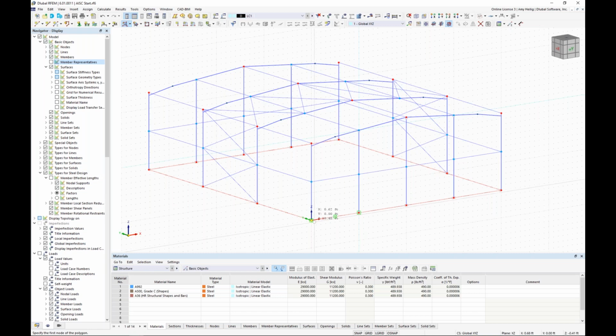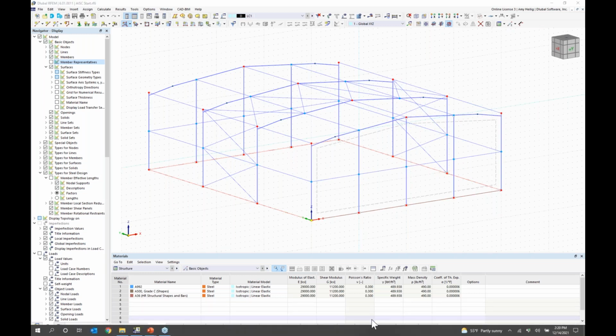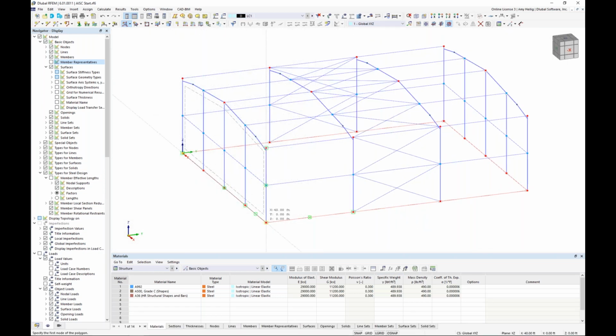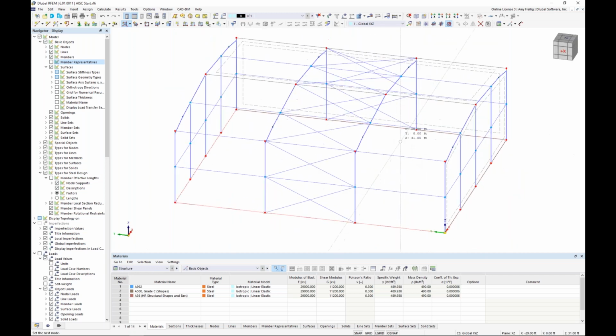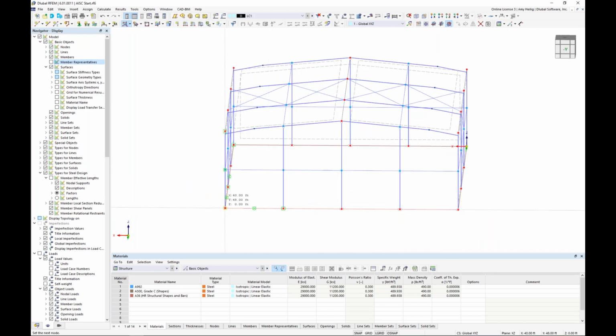So what I want to do here is to go ahead and snap to the coordinate points here of my surface for my front wall. And I'll go ahead and turn off my drawing grid here down at the bottom just to make this a little bit easier. Now, currently in a rendered view or a wireframe view, it's a little bit difficult to see these surfaces. You'll notice that only a dotted line is created. And every time I'm closing the surface with that final point, I just double click. We'll go ahead and generate the surface at the left side of the roof here. And then we have one more surface to generate here at the back.